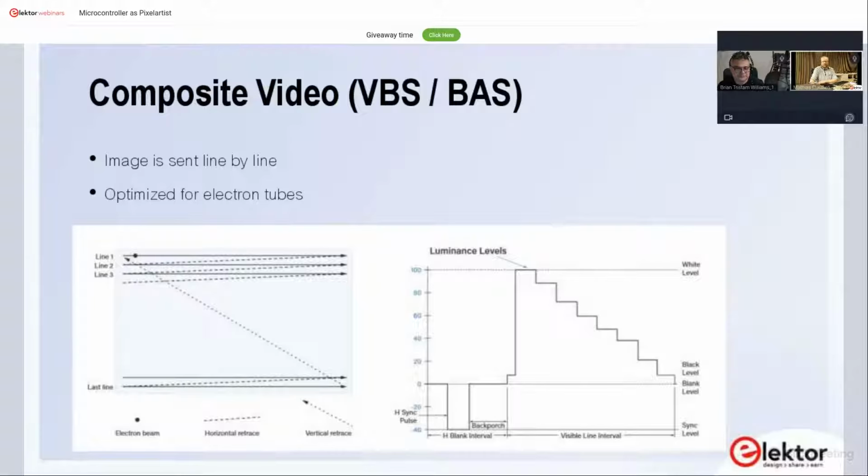And looking at the timing information, you see you're starting top left and going down to bottom right. And if you look at a modern digital image, you will still find the first pixel at position 0,0 top left. So the origin is different to how we learned in school, where the origin is bottom left. Yep, so they start top left and then run around the screen line by line until they reach the end, and then they start again. And as you can see, it looks really simple. And if you're just going black and white, it sort of is.